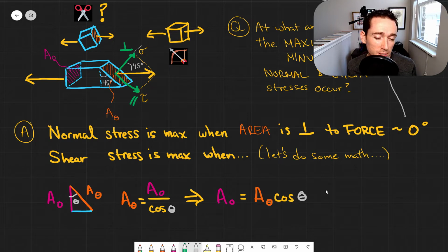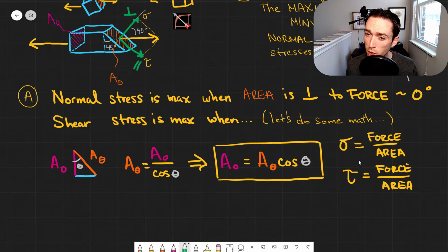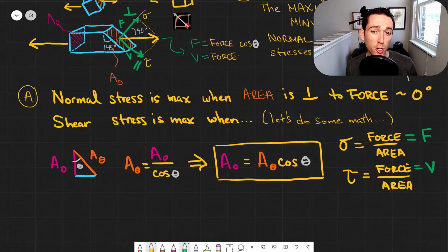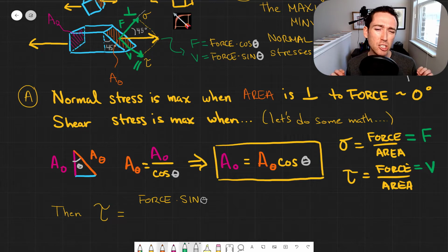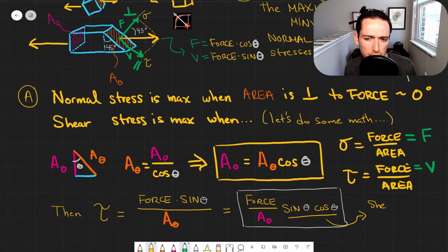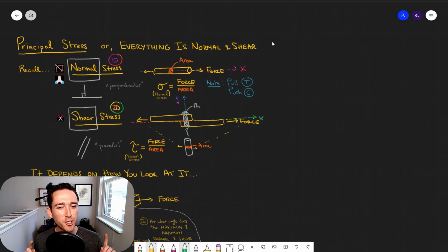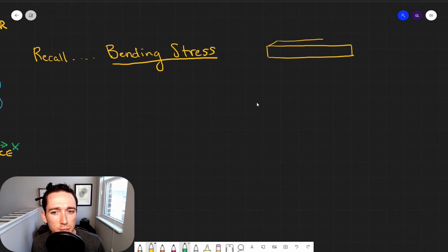And, recall a little bit of classic trig. We can actually get a relation between these two. Recall the equations we learned above. We're just going to label a few more things here. Recall some vector mathematics. And then we're going to put all this together to look at the shear stress. When we put it together, we realize, wow, this is just force over area with this additional term, sine theta cosine theta. When's that max? It's max at 45 degrees. So this is so interesting. We're seeing normal and shear everywhere. Where else do we see it?